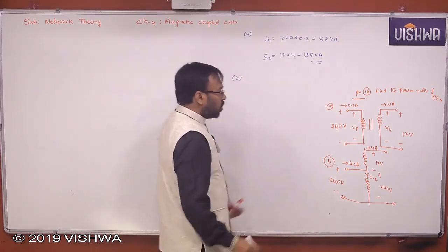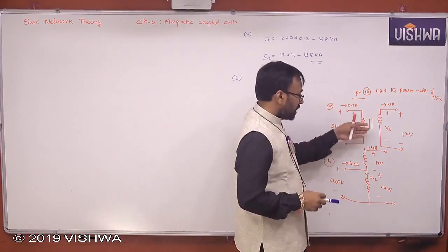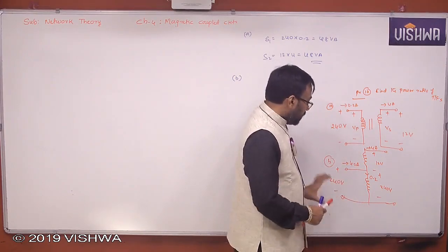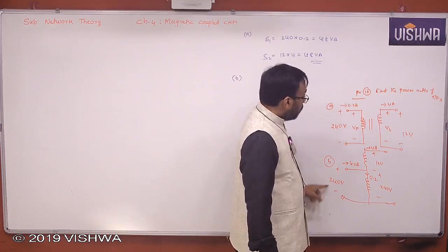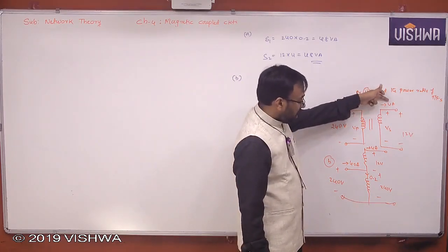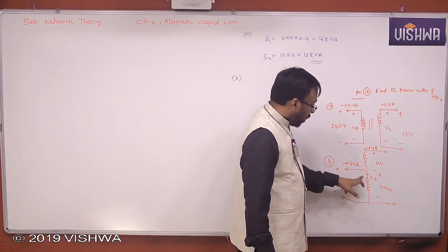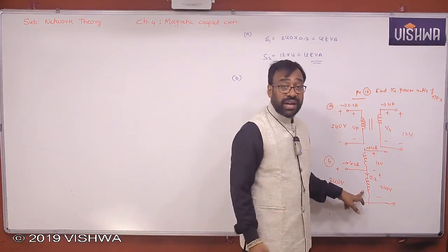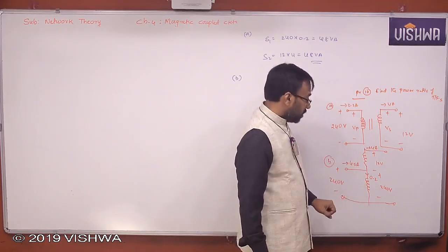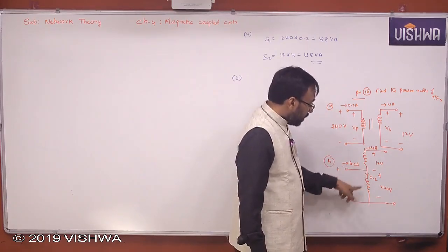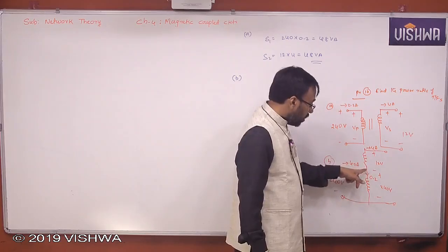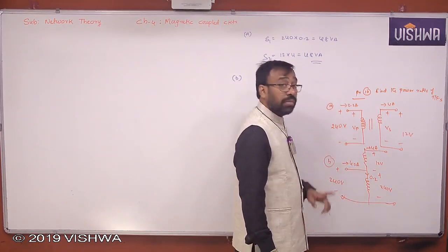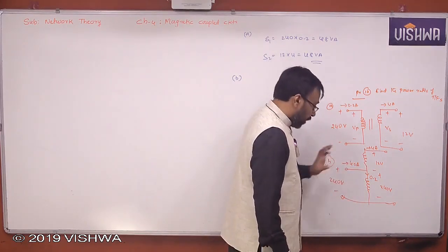Now B, the same two winding transformer, or two leg transformer, is constructed as an auto transformer. On the single leg they placed it. Now you see the primary side is 240 volts, but this was 0.2 ampere, this was 4 ampere. Assume that once it is connected, 0.2 amperes is flowing through this winding. 0.2 ampere is the rating of that winding, and 4 ampere is the rating of this winding. Then obviously when it is connected like this, when 0.2 is flowing here, how much will be flowing there? 4.2, because 0.2 and 4 are both leaving. Agree? All of you? Then 4.2 amperes.